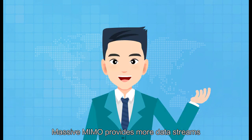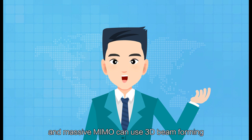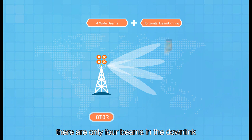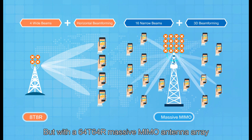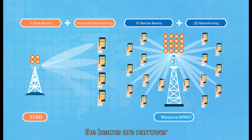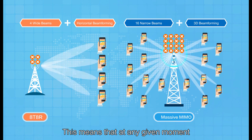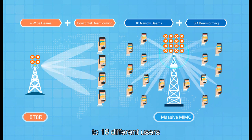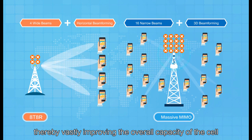Massive MIMO provides more data streams than can be provided in a traditional 4G 8T8R antenna array, and Massive MIMO can use 3D beamforming. In a traditional 8T8R setup, there are only 4 beams in the downlink. But with a 64T64R Massive MIMO antenna array, the beams are narrower, which makes it possible to create 16 different streams. This means that at any given moment, the G-Node B can allocate the same time frequency resources to 16 different users, thereby vastly improving the overall capacity of the cell.